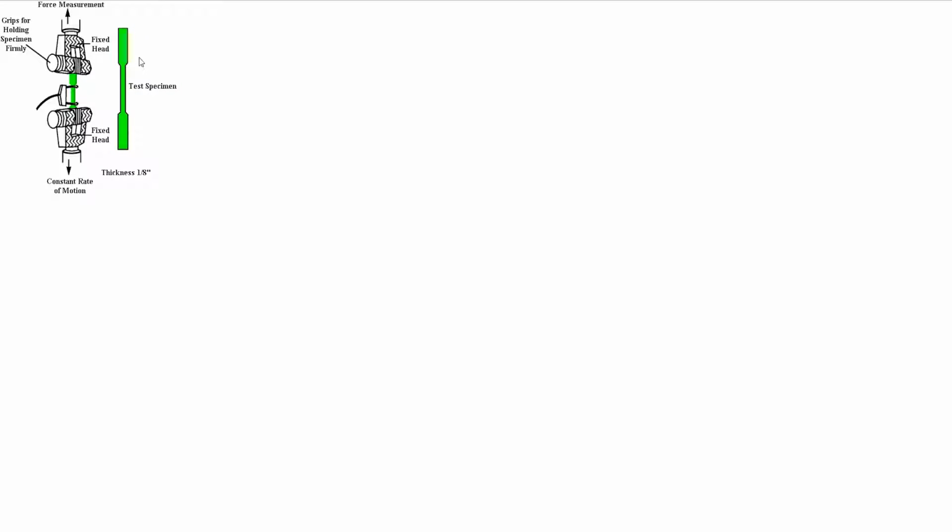This is a tensile tester, so you have this eye-shaped sample, and you put the top of the eye here and the bottom of the eye there, inside these clamped heads. One clamp will stay fixed, the other one will pull. Tensile is pull, compression is push. It will pull and deform your sample, and it will have a load cell to measure how much force is being applied. It'll also have an encoder that will read how much distance it's been pulled.